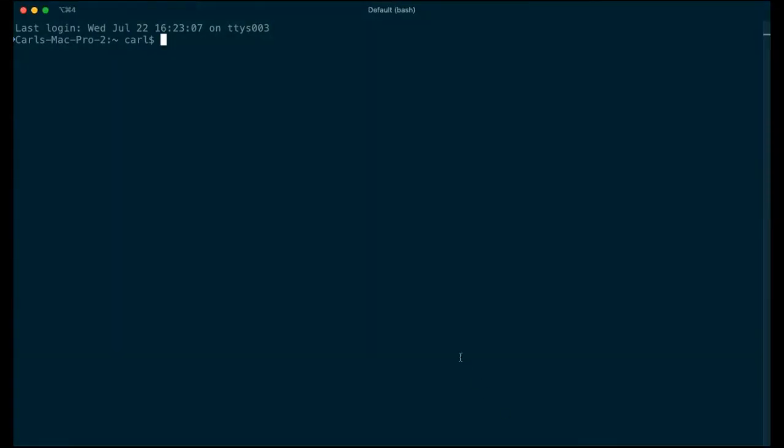So let's actually play with some of this. I have a dongle attached to my computer here, and we'll give it a run. There are quite a number of tools and programs available for looking at or handling SDR. Some of the most useful ones on the command line for looking at RTL dongles in particular is the RTL-SDR toolset or library. There are also variations on that called the RX Tools, which take the RTL tools and modify them to support a greater number of SDR receivers. In our case, however, we'll just look at the RTL tools.